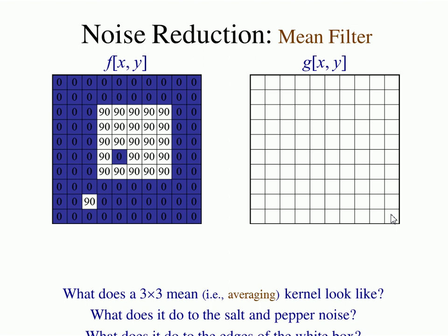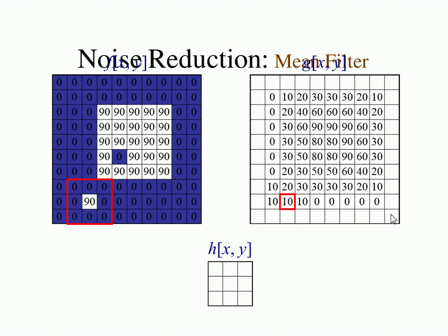So here's that sort of 3x3 mean filter, and I'm going to say that, does this work? It's sort of working. That's a 3x3 mean filter, so they're all ones. And then you divide through by a ninth in order to normalize.